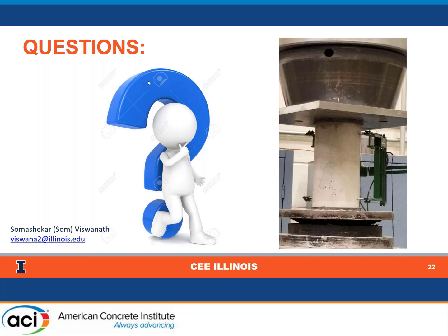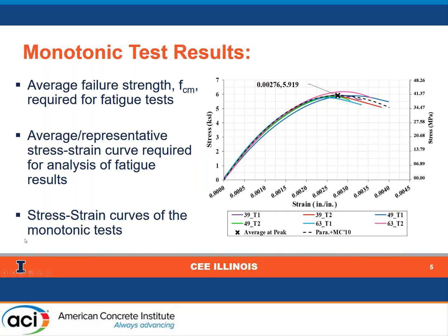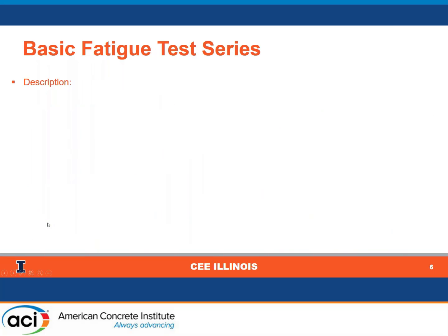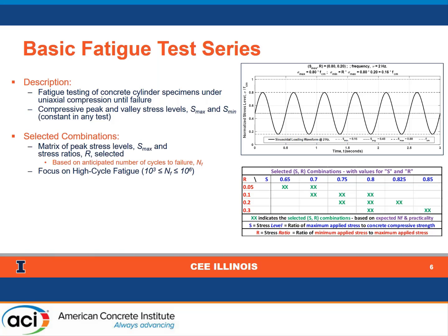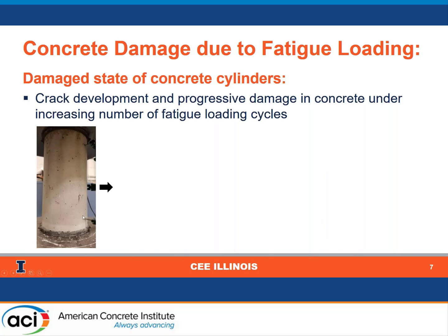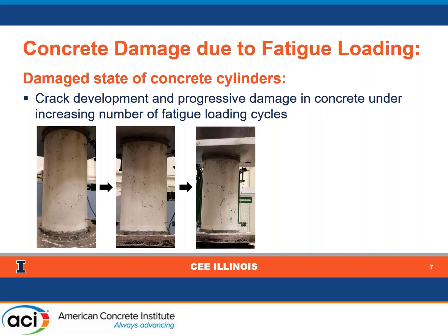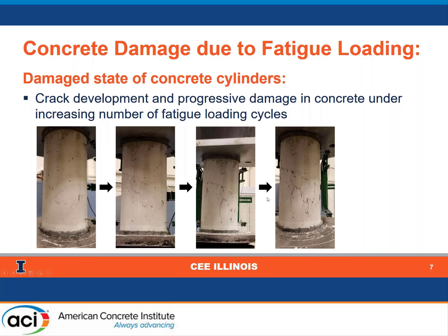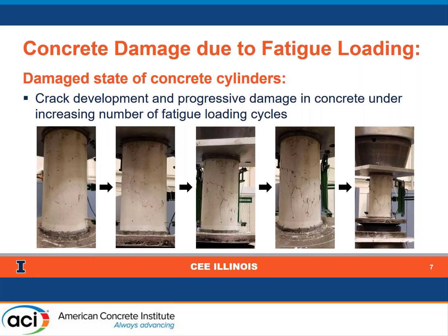When we did the fatigue test, initially we started seeing the surface cracks develop at roughly about 60 or 70% of the failure number of cycles. And with increasing cycles, we started seeing the cracks become bigger and bigger. So there was definite damage in the specimen. So we were just referring to this as fatigue damage. And because we saw such big cracks, we hypothesized that there must be some other effects on the behavioral aspects, specifically strength and stiffness, which is what we investigated in this investigation.